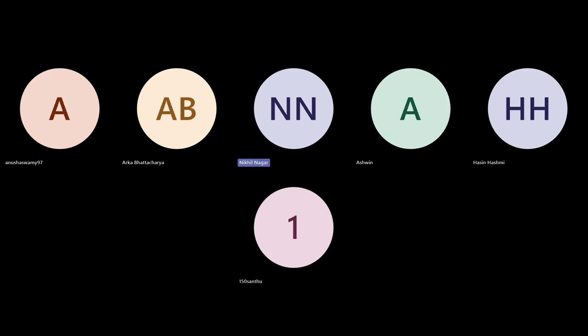In 5, you can change this bay length also by clicking on that, but take care that the total of this bay length should be equal to the total length. Click on apply. So this is the structure that I have prepared in our structure. Click on cross, click on yes, click on OK.